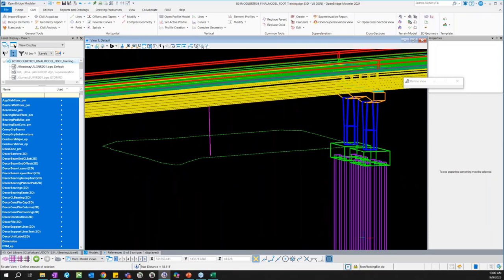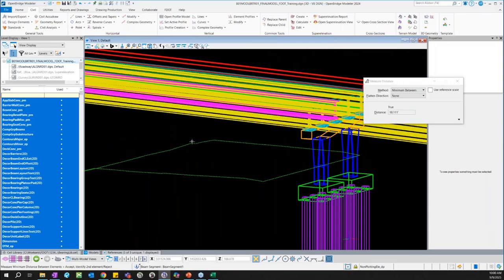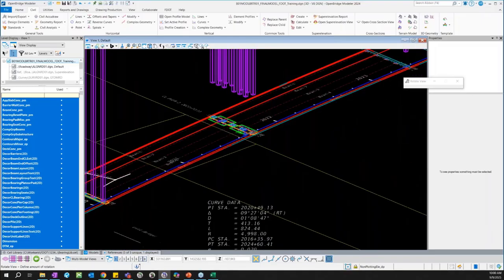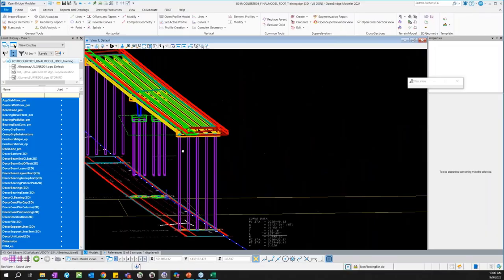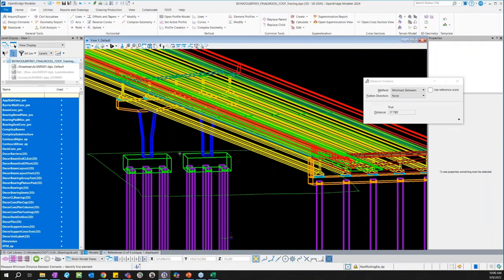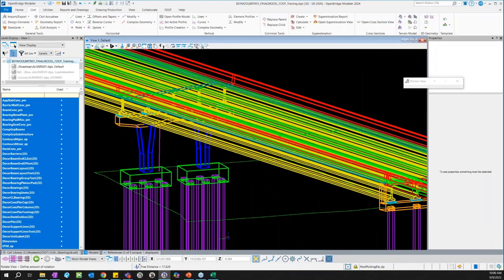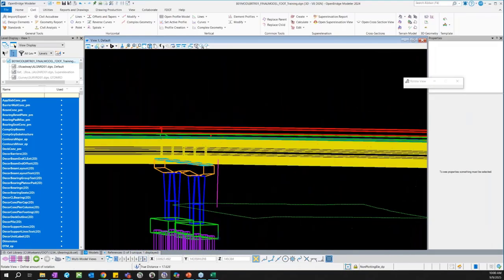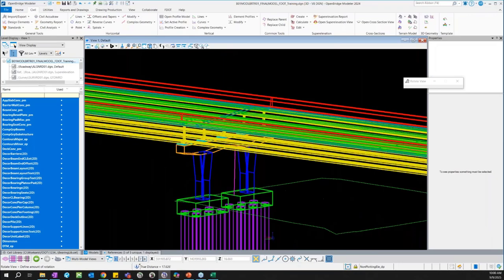You can go through and check a couple different spots: 17.917, so we can see that's less, and then 17.785, even less. That's telling me that this other side is likely the one that controls. So use this beam, select this terrain, 17.626, so that looks good. So this is our point here.